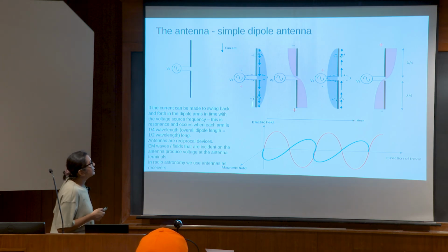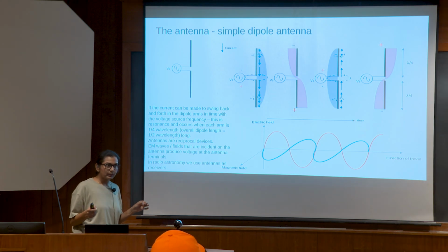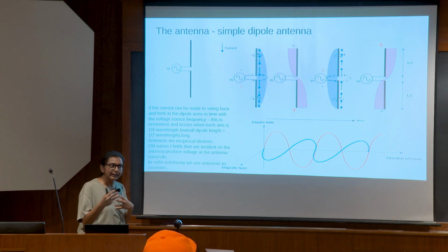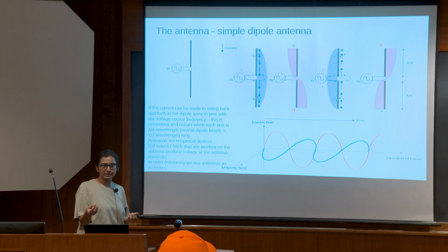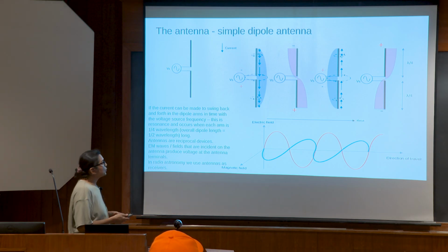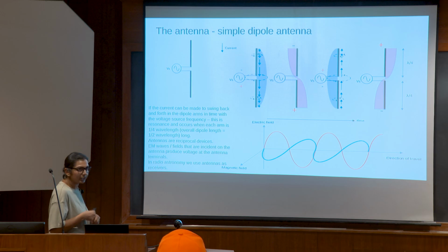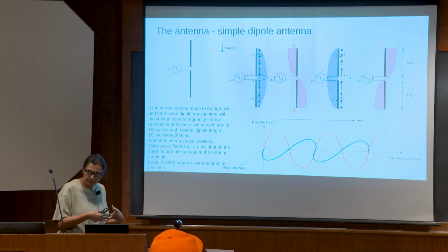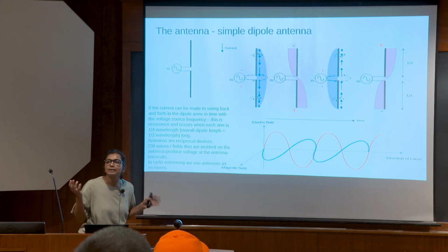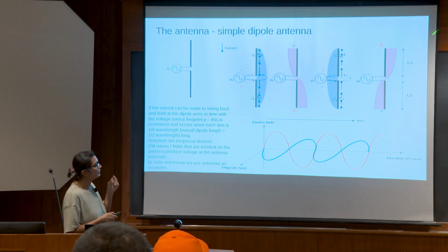Because there is a certain natural length of the wire and the frequency involved, this dipole will be efficient at radiating or receiving at a specific frequency, okay, and that's the resonant frequency of the dipole, okay. So for a certain frequency of radio wave that you are, let's say, sending or receiving, let us say that the corresponding wavelength is lambda of that frequency or that RF signal.